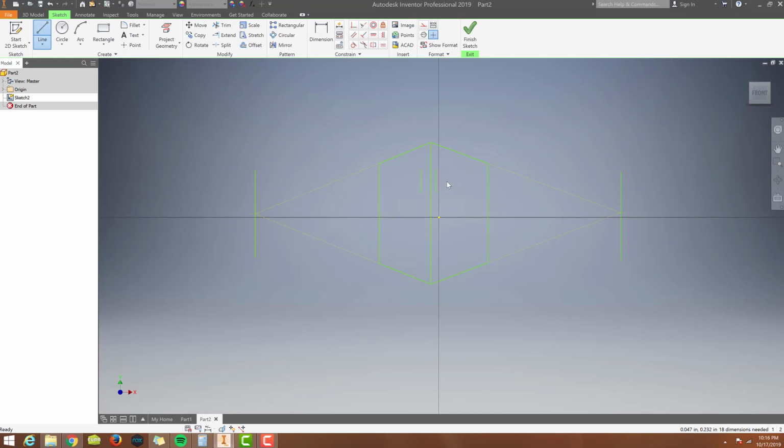Okay. And once again, what we just did was we drew a vertical line. So whenever you draw a vertical line, you want to then turn on your construction lines, and you want to bring the top point over to a vanishing point and the bottom point also over to a vanishing point. Okay, and we could bring it to this one as well, but because these windows are going to be on this side of the building, I'm not going to bring it over to the vanishing point on the other side.